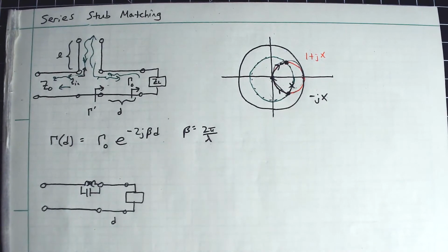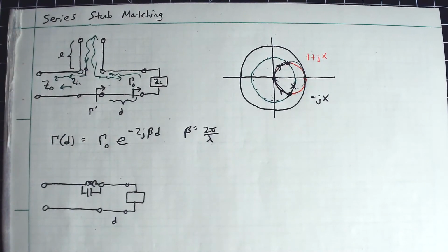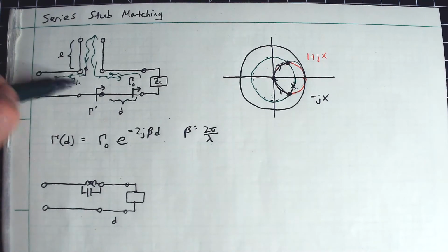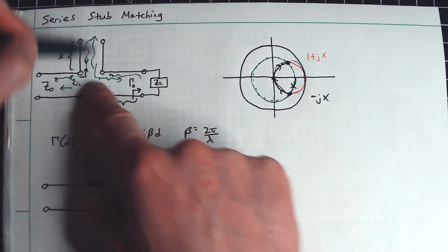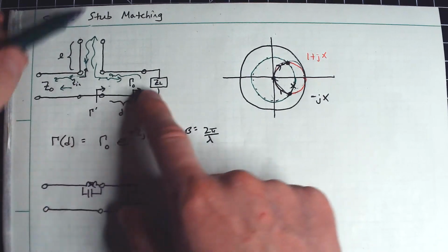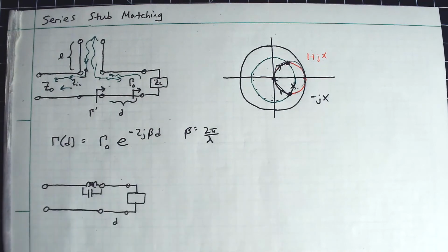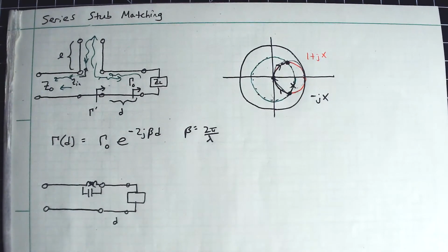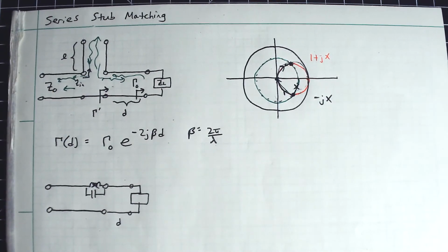So it's that same concept that we saw with the quarter wave transformer, where you had those signals kind of infinitely bouncing back and forth, and the net transmission back in the opposite direction all just destructively interfered the original reflection from that initial bounce. So this is a similar kind of concept, only you have these two waves kind of bouncing around on each other. But if you get all the lengths just right, they are essentially destructively interfering with that initial reflection, and you get a match at a very specific frequency. So it won't work for all frequencies, but it will have a pretty decent bandwidth depending on your application.